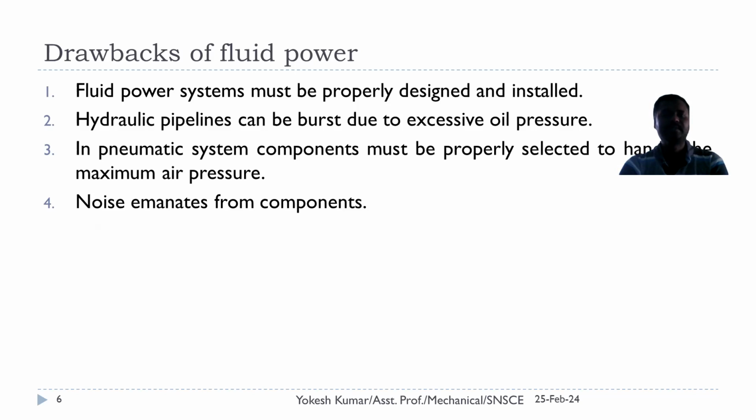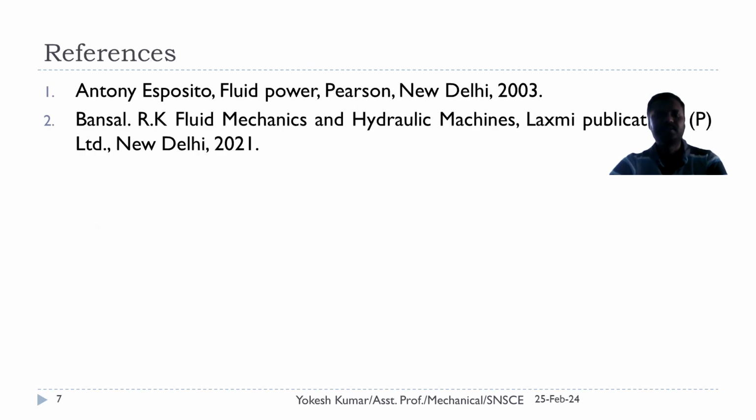Noise emanates from components. It is not there in the hydraulic system, but it is a major problem in the pneumatic system. Even though we use suitable silencers, we cannot completely eliminate the noise, but we can reduce its intensity in the system. So these are all the drawbacks in the system. We must consider these drawbacks while designing the circuit.